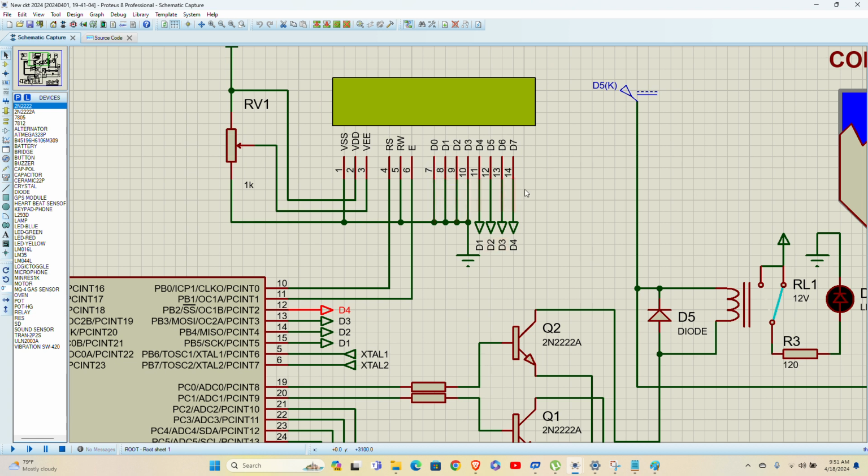So it's the same. We used only 4 pins because we have discovered that we can use 4 pins to display any character we want. Early, before this discovery, we used all 8 pins, which was called the 8-bit configuration.